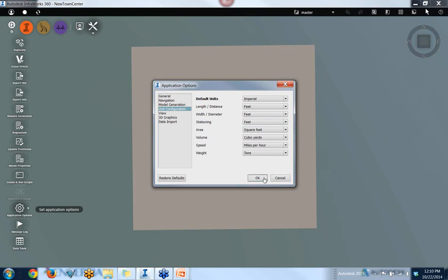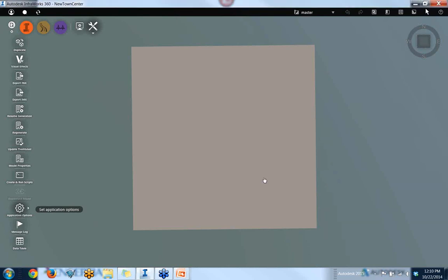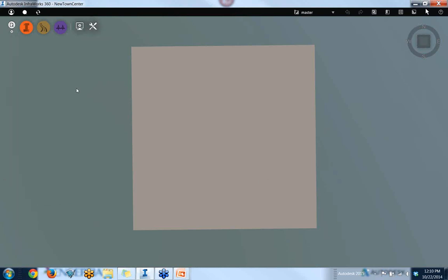Now that I've got this set up, I'm going to bring in my existing condition data. The idea here is I've received a number of GIS data files from the local government that I can use to display the existing conditions. When I import the data, it's going to be imported, and then I have to configure it. Since all the data came from the government, in this particular case, I'm lucky that all the data has the same coordinate system, but I'll explain along the way why that's critical.